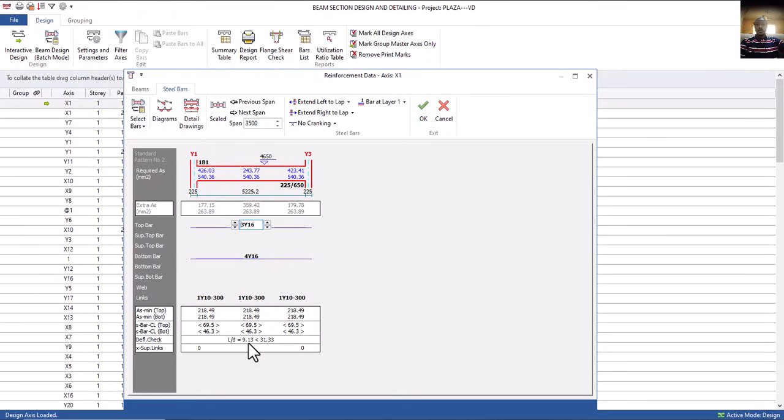Even in manual design, if your actual is 25 and your limiting is 26, the difference is just 1. And normally in manual design we say the section is okay. But when it comes to reality in design, using software or designing in real life, that 1 is too close, because any slight mistake or compromise at site can lead to deflection. Is that okay?